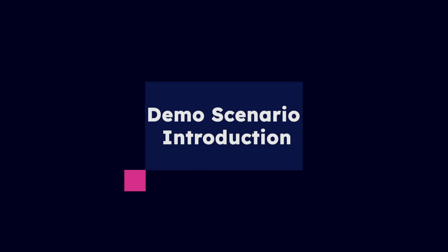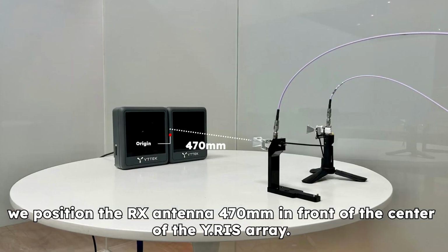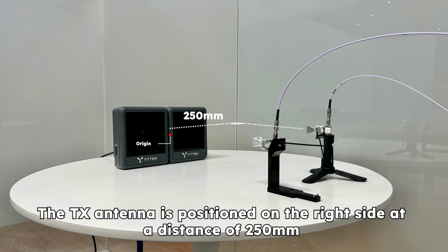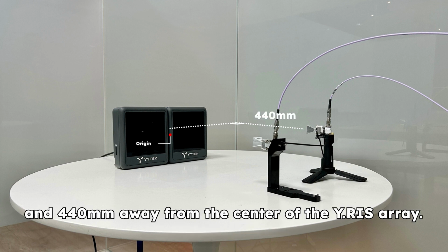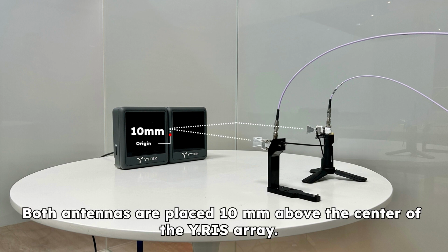Demonstration Scenario Introduction. In this demonstration, we position the RX antenna 470 mm in front of the center of the Y.RIS array. The TX antenna is positioned on the right side at a distance of 250 mm, and 440 mm away from the center of the Y.RIS array. Both antennas are placed 10 mm above the center of the Y.RIS array.